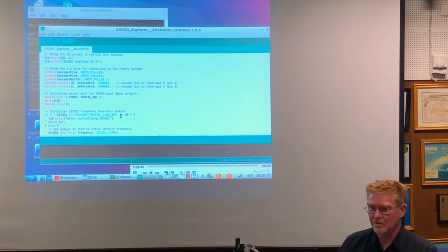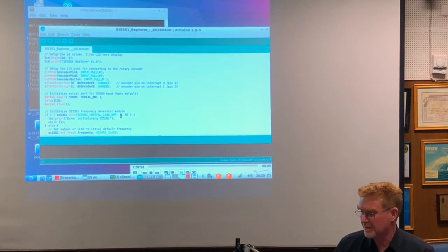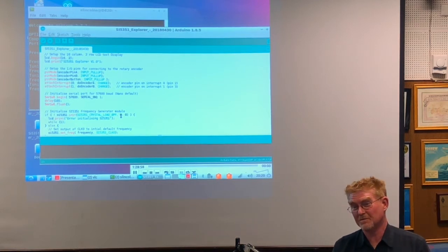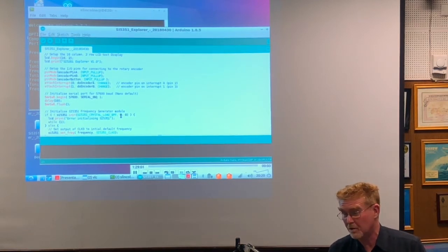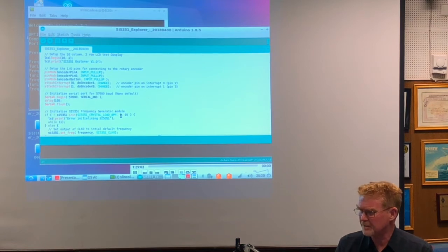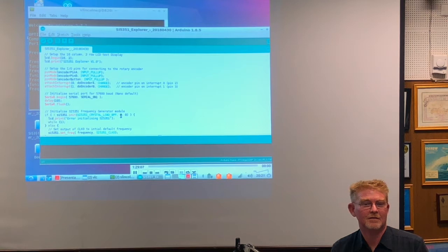But again, you've got all the environmental factors and so forth, and it may not be what we're looking for, but like I said, this is being used for the micro bit-X transceiver. It's good enough, I guess, for QRP purposes. Not good for microwave use, but the frequency range of this is actually quite low. That module, I think the upper frequency limit is about 200 megahertz. But if you can do the comparison, you'd be able to feed 10 megs, stabilise 10 megs, and then do the comparison and the correction.